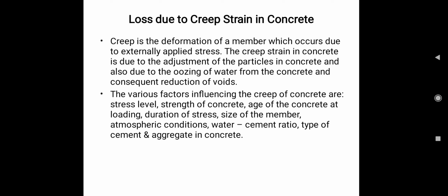So here, in case of pre-stressed concrete structures, concrete remains under the action of continuously acting thrust due to the presence of tensioned steel. Under the action of this thrust, concrete undergoes permanent deformation because of constant tension.